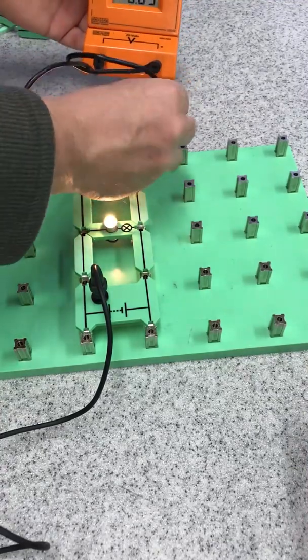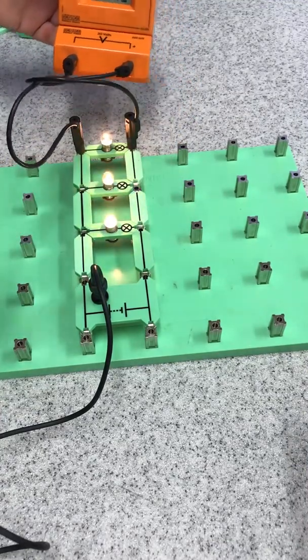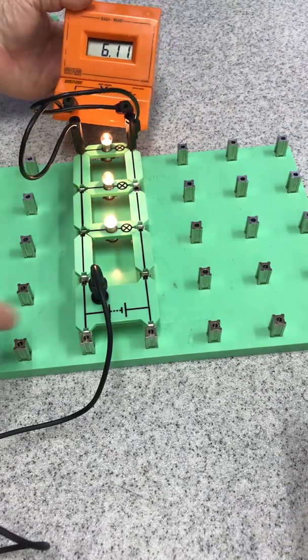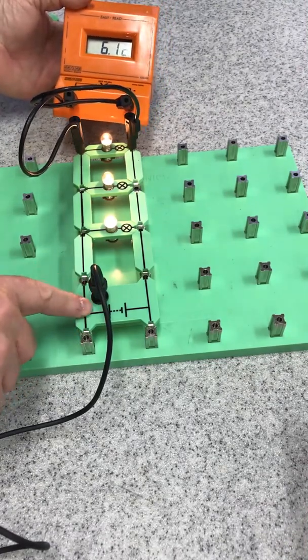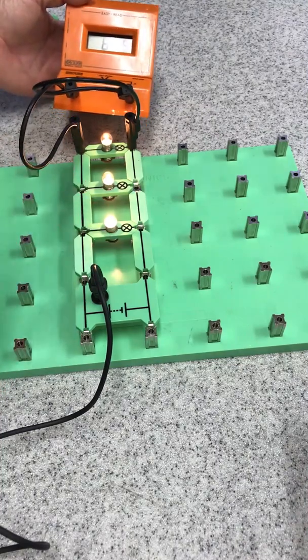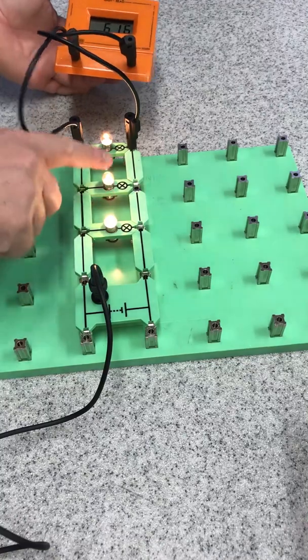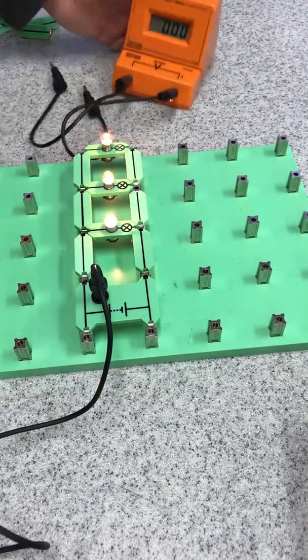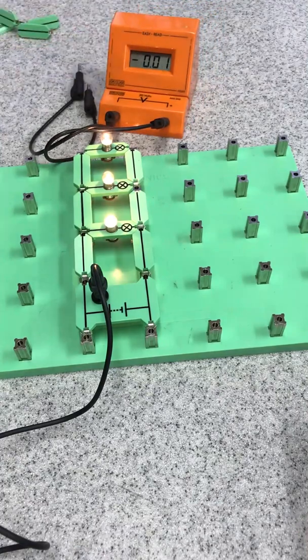So all of these lamps are getting their full allocation of energy. They're all receiving the same energy as given out by the power supply, because the electrons only pass through one component, be it that lamp, or that lamp. They don't pass through all three as they did in the series circuit, so they had to use some energy in each of the components.